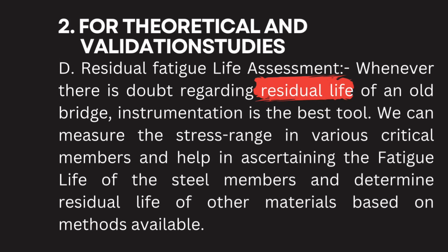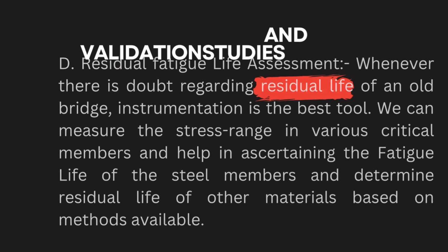D. Residual fatigue life assessment. Whenever there is doubt regarding residual life of an old bridge, instrumentation is the best tool. We can measure the stress range in various critical members and help in ascertaining the fatigue life of the steel members and determine residual life of other materials based on methods available.